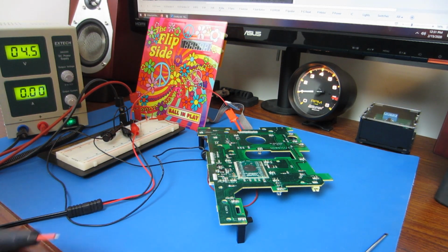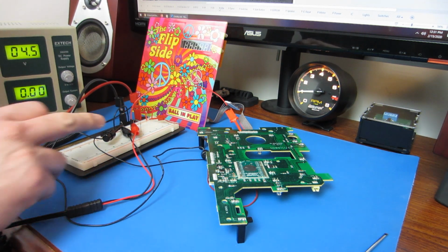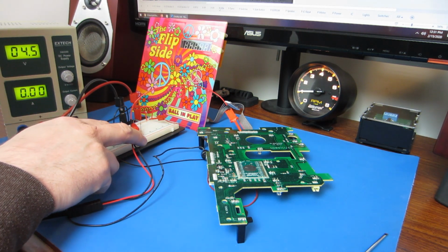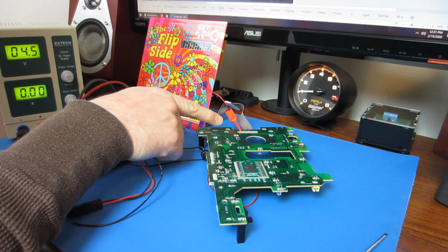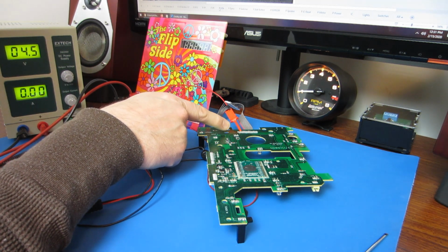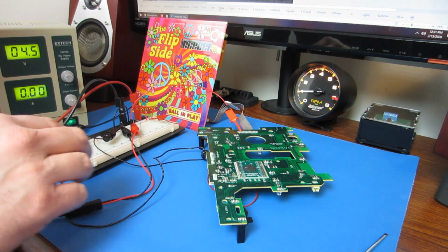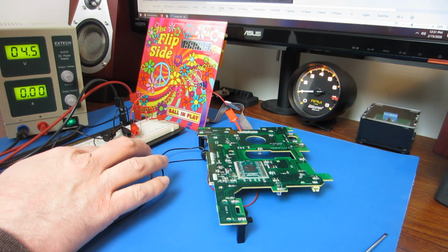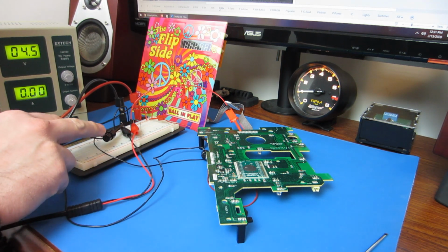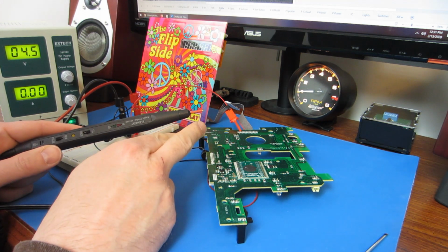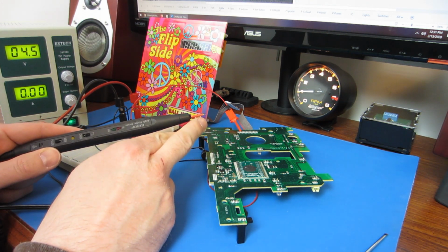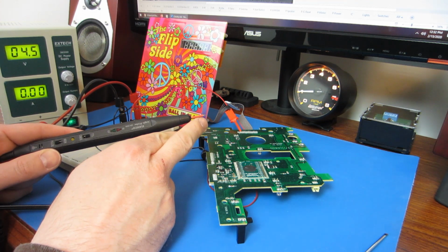Okay, all hooked up. So the probe has 3 connections. There's the positive voltage of the unit that you're trying to test, which I've got hooked up to the VCC lead next to the SPI bus. Then there's the ground connection of the unit that you're trying to test, which I've got connected to the main battery ground. And then on the probe itself, this is the lead that you place on the trace that you're trying to test.